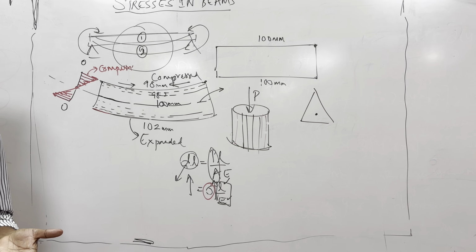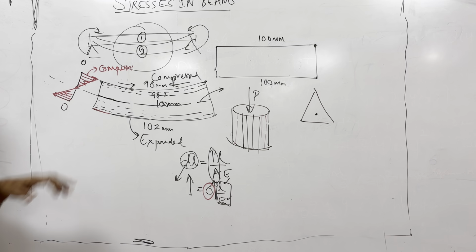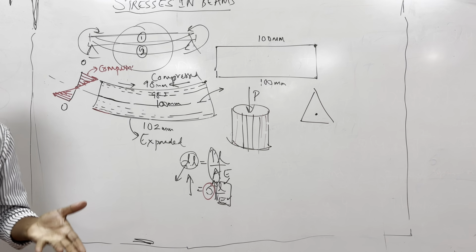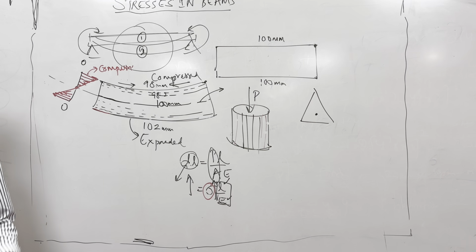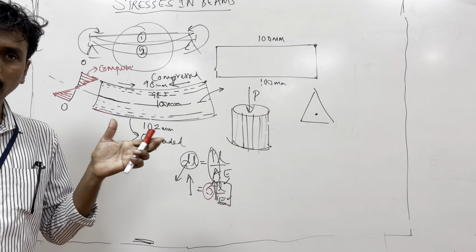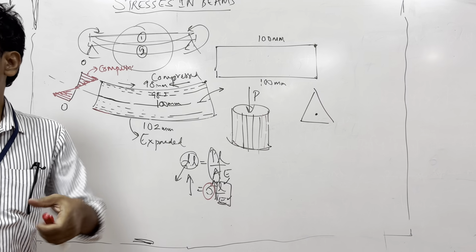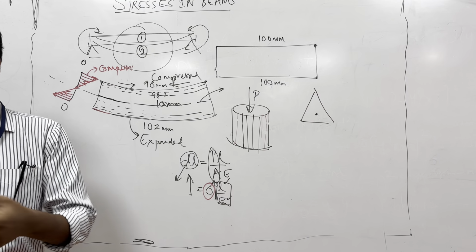So therefore, it is very easy for you to induce huge amounts of stress by bending. It is very easy to stress a member in bending, where some fibers will have huge stresses. That stress may go beyond their allowable stress or what the material can take. It is the reason why, if a bike falls, do you feel any component would crush under compression? Most of the failures are under bending. Your handle bends. Your pedal would bend.